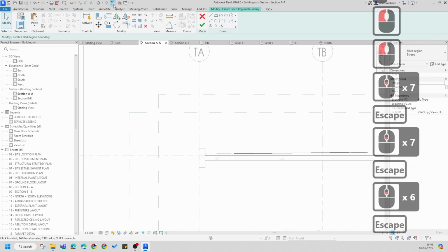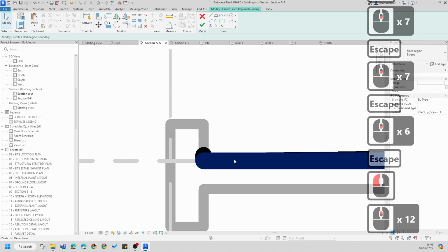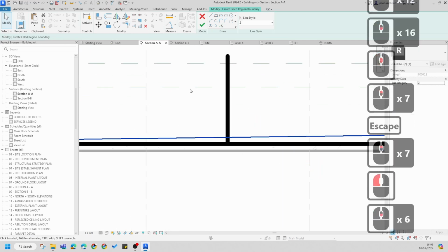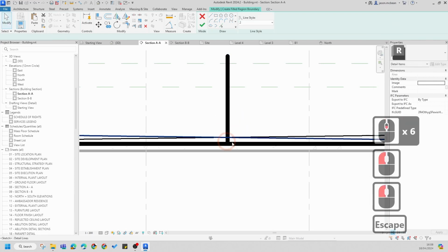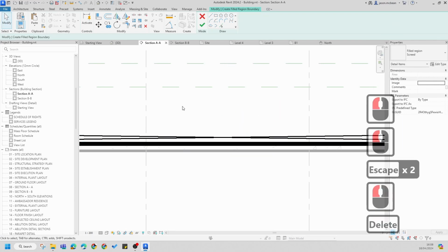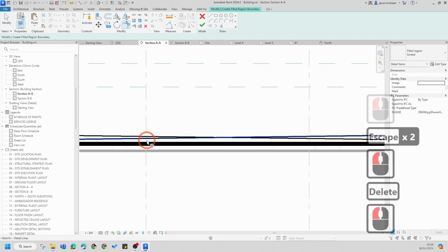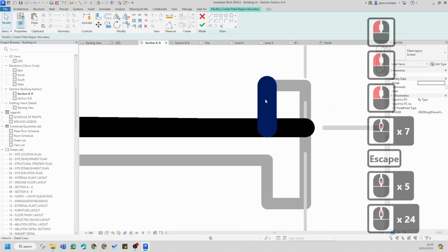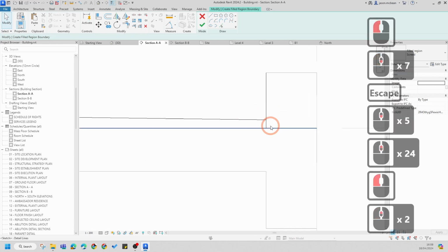So if I switch on line weights now, you'll see that I've got a thin line and a thick line, and I can mirror this line in that direction, mirror that around this point over here, and I can delete that now, and I can use my trim command. I'm just showing you very quickly how you can show screed to fall. Okay, switch this back on, trim.